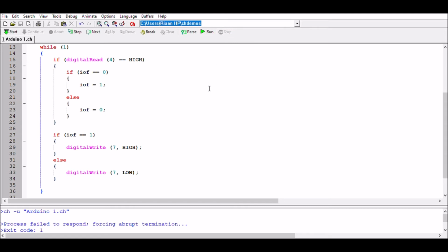Alright, so as you saw, the code runs very quickly and goes through this while loop numerous times. It toggles between 0 and 1. The pull down resistor was very much needed, as you would have seen that the light toggled because there was no indication to the program whether the input was high or low. It could have been the contact points clapping against each other, which makes it on and off all the time, or it could be some capacitance on that pin that needs to discharge before it allows the final state to happen. So that's the reason why the pull down resistor is very important.